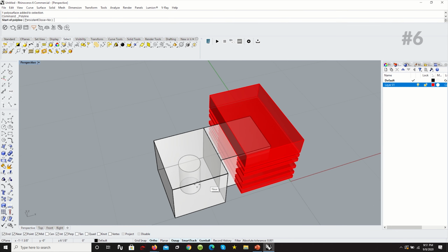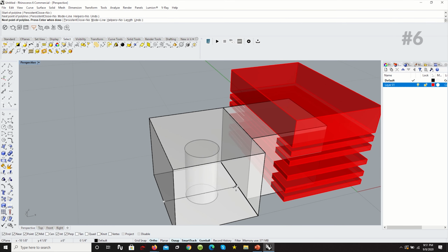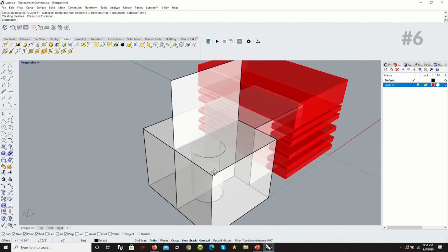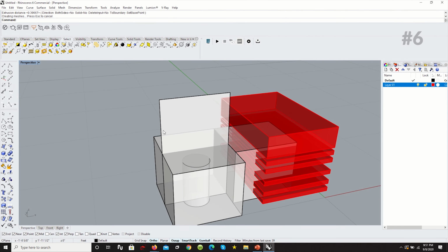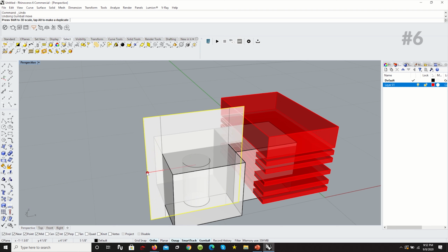And you can see it more so like this. Let's use a line. Let's click here, going from this end to that end. And now we can select this line and actually extrude it. When we're about to split an object, we want to make sure the line is passing completely through the object. Going beyond the surface is something I do to make sure it's accurate and it's actually going to cut through the object. So we just drag this down using the Z axis on the gumball tool, and we can begin to expand it a bit by dragging the end point of the X axis.